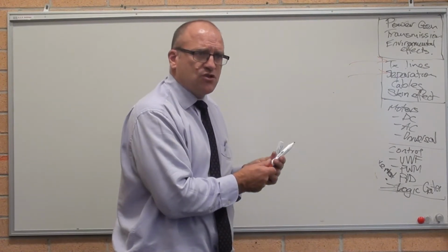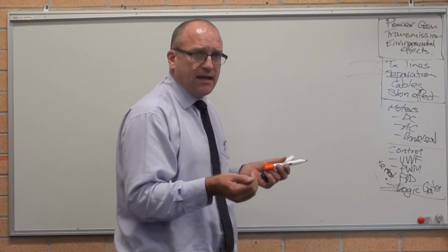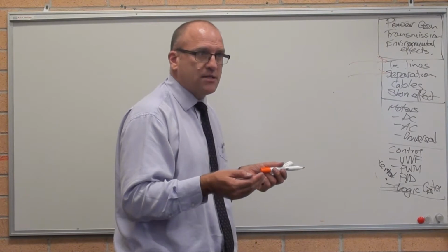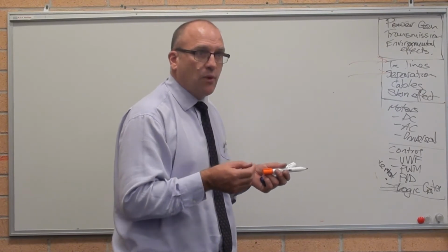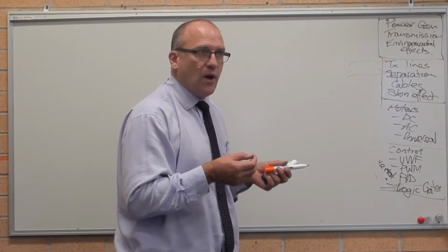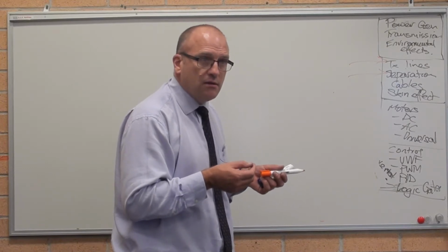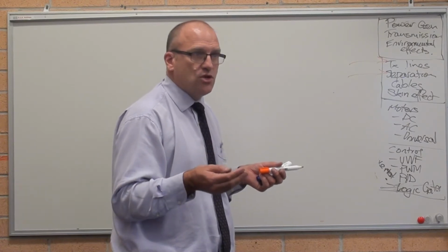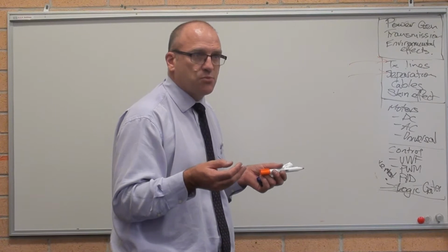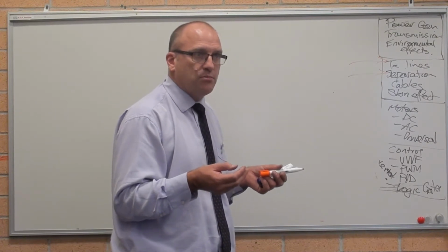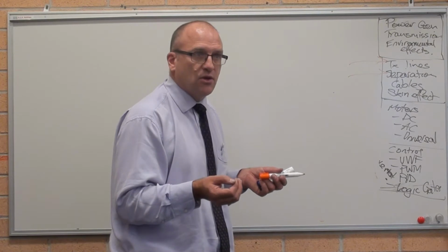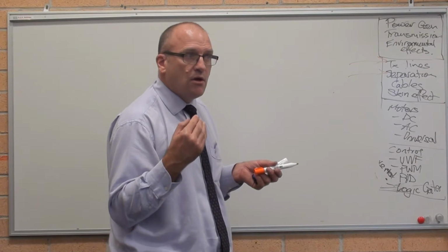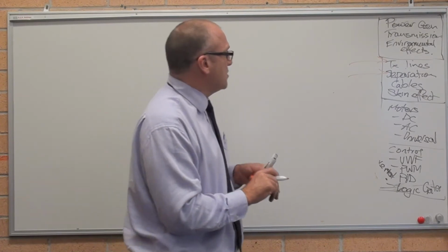When we were working in industry, if you've got an 11 kV transmission state, you're fault finding 11 kV, you are basically standing at least 8 metres away looking, unless you are absolutely sure the thing is dead. If you're running at 1.1 kV, 1100 volts, you do not go any closer than 3 metres to the switchboard if you're trying to find a fault, because if you go closer, you might become the earth. So voltage does throw distances. Voltage is the driving force, it throws distances.